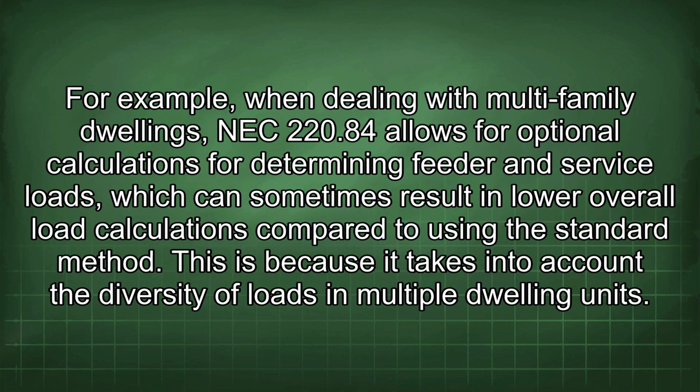For example, when dealing with multi-family dwellings, NEC 220.84 allows for optional calculations for determining feeder and service loads, which can sometimes result in lower overall load calculations compared to using the standard method. This is because it takes into account the diversity of loads in multiple dwelling units.